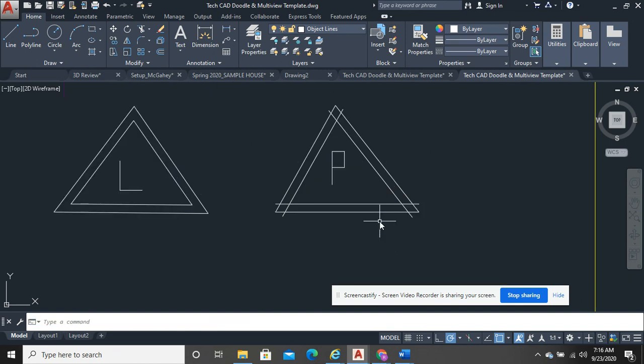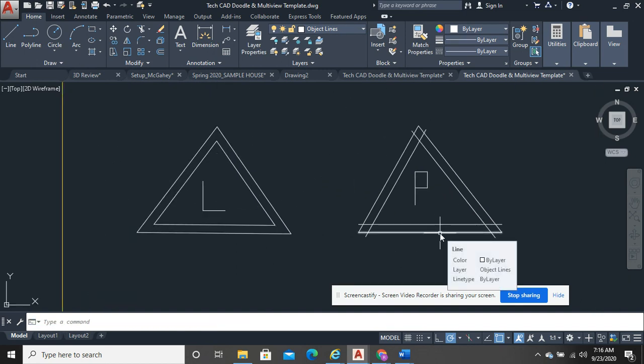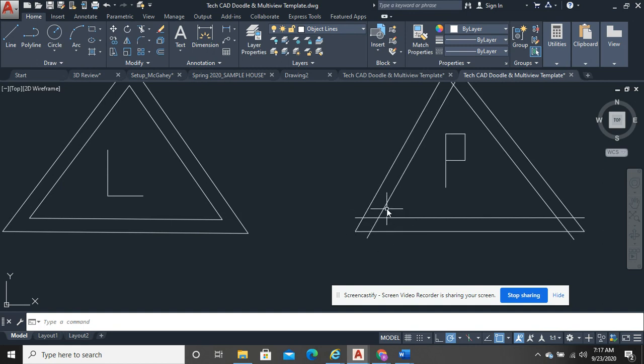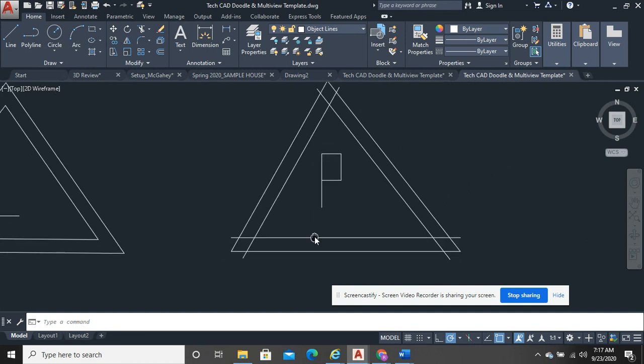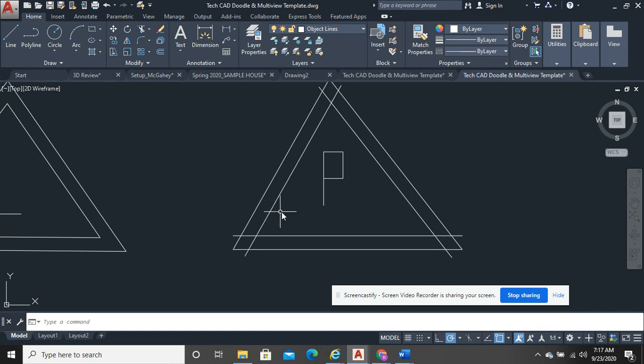Okay. So the joining and exploding, you can tell one thing was advantageous to me, and that's that joining it, okay, made this one entity, and it made that copy exactly the same, but it didn't bother anything in here, right? It didn't make all this crisscrossing in here, okay? The one that was unjoined, the one that we had exploded, now has all of this nonsense. And if we want this to look like this, we have to get rid of it, okay?